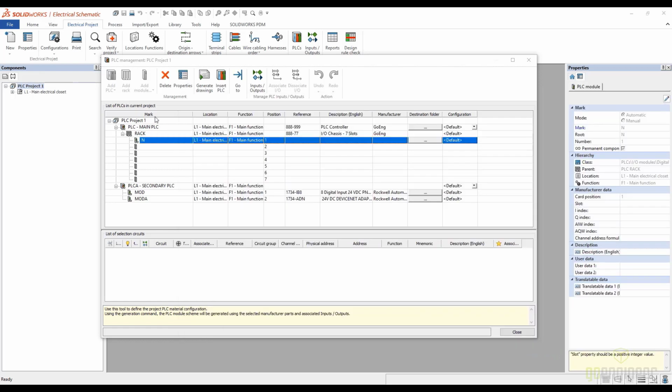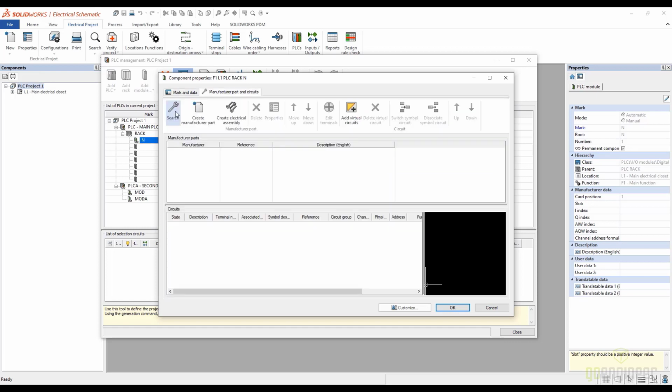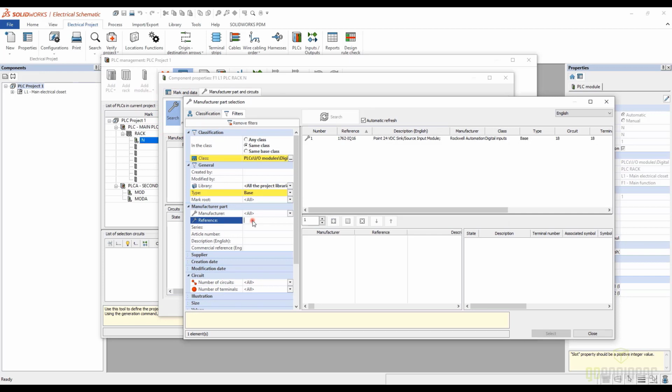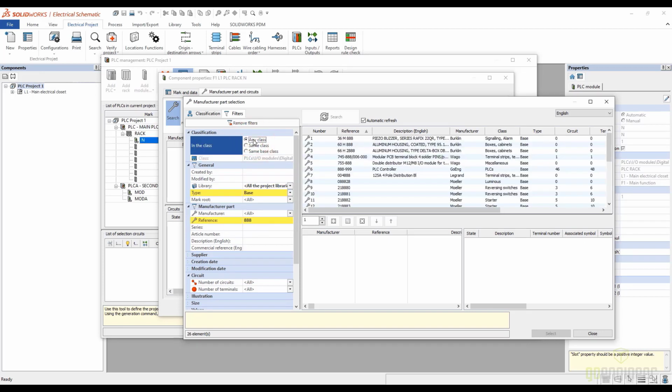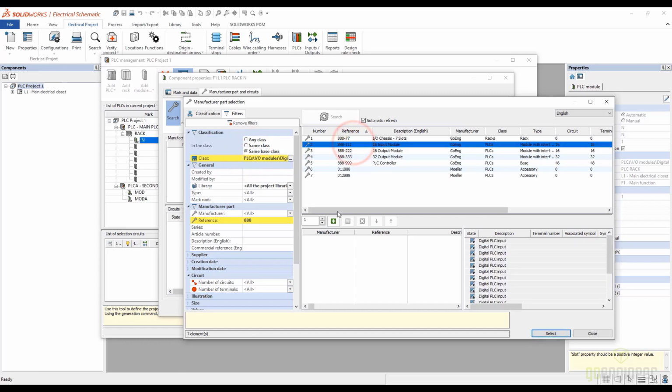We are only going to add one at a time. Now, the one thing to keep in mind, notice that there is a card position already being selected when I am selecting the specific position in the rack. Never are you going to try and force a card position to another spot. You want to leave it where it was. So here I'm just going to grab a module or another module, this time another 16 input, and place this.